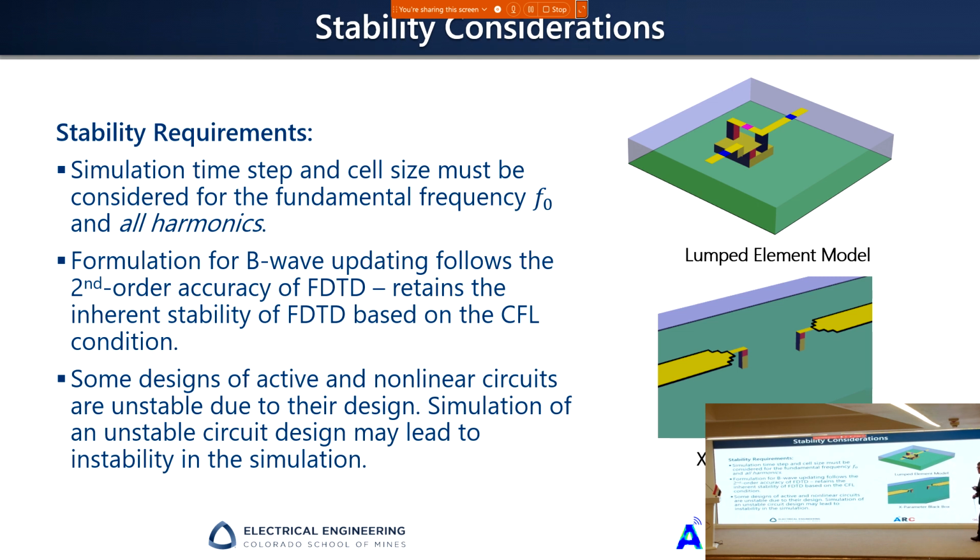So this is basically what we have done. We managed to characterize the behavior of a nonlinear device, extract the X parameter from a finite difference time domain simulation, use this extraction in a black box, and put it in a finite difference time domain simulation, run the simulation and confirm the results.